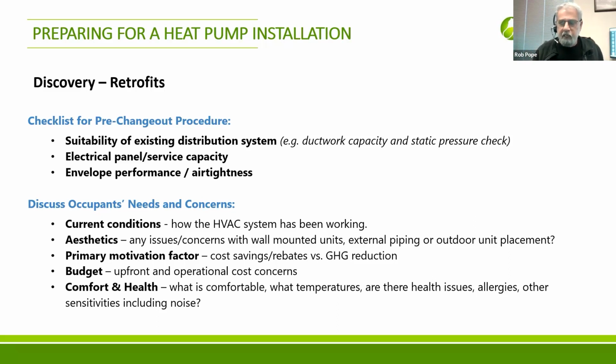And envelope performance and air tightness. You want to get an energy advisor in there if you can, do a blower door test, and check the building for other things like its insulation values, especially on a retrofit with the intention of improving the building itself. You might be changing that heating equipment out because you're doing other things.